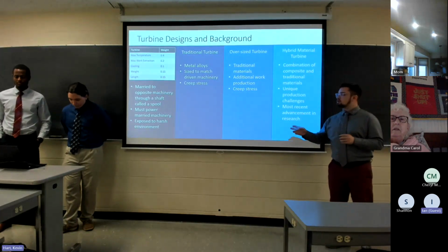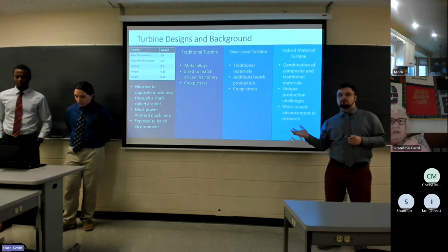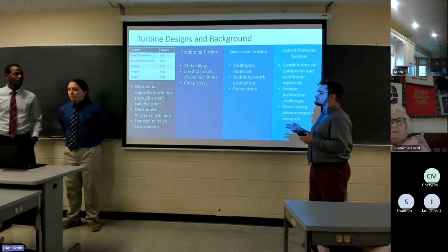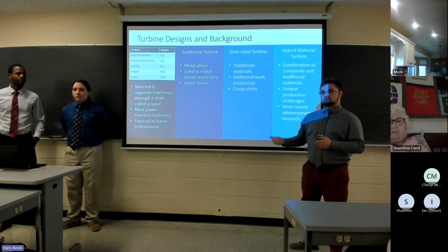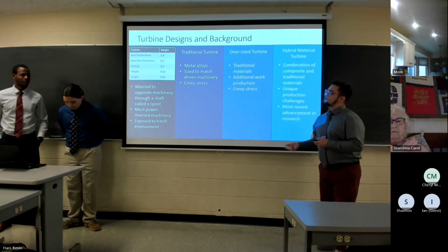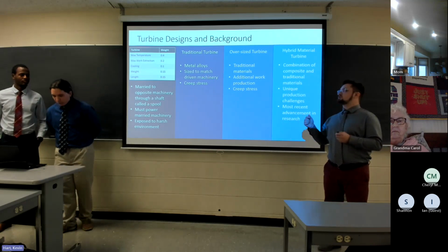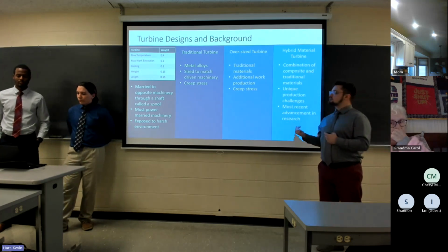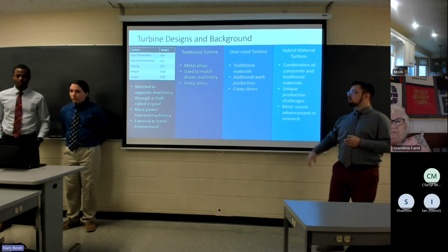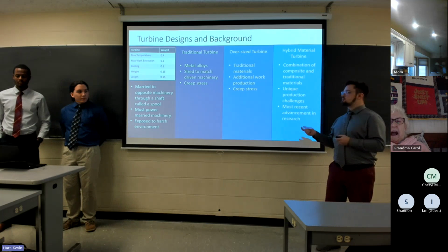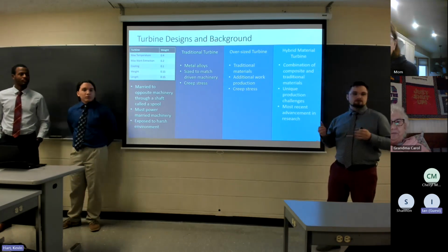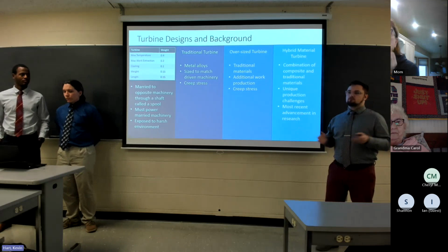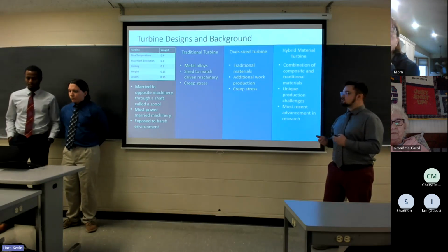So again, as aforementioned, the turbine drives other machinery. It is the primary mechanism of mechanical energy harvesting, essentially. We wanted to look at the max temperature because it's directly outside of the combustor. We need to look at the max work extraction to drive each component, so the fan or compressor. Since it's getting blasted by that hot air, you really need to focus on the cooling. By doing that, you can maybe push the temperature that it can see a little bit higher. Again, weight and length need to be considered to help reach the RFP specifications and constraints.